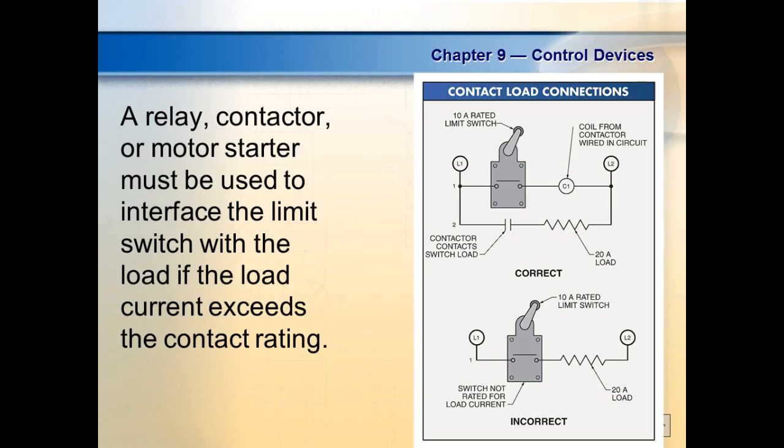So the PLC could make all the decisions inside the PLC to determine when a motor runs, but the PLC could not run a motor. It can output enough current to bring in a relay that does what? Runs the motor. So PLCs have not done away with relays. What it has done away with is all the relays that don't require power contacts in the power section.